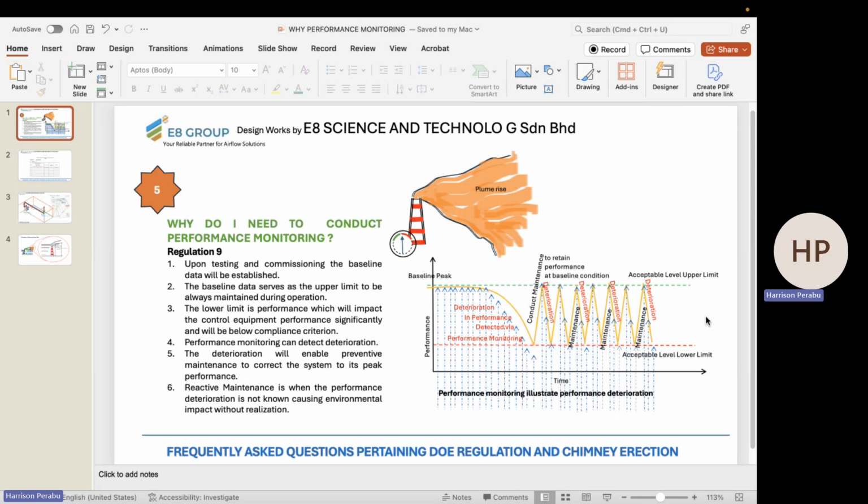Aerosols come in various types. You have particulate matter. Aerosols are anything less than 100 micron, which can get suspended, which can get into the respiratory system, or when it gets into a system, it can clog the system because these are particulate matter. It can close pores. Now, if aerosols, especially particulate aerosol, or sometimes liquid aerosol or fumes, which are a type of aerosol, go into an activated carbon, it will close its pores and it will clog the system.